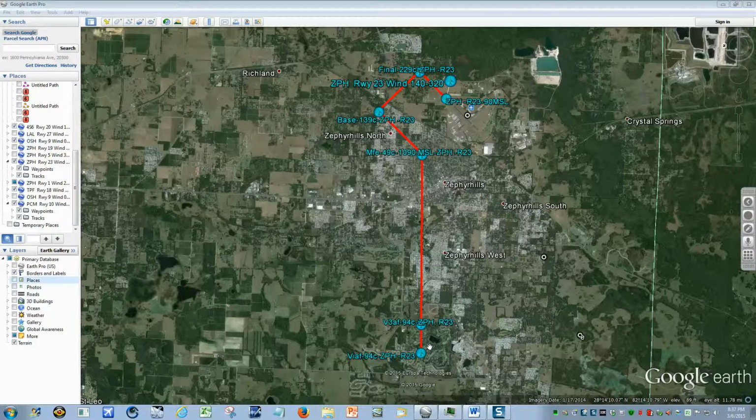Using our conservative 8:1 glide ratio, we multiply our anticipated altitude times 8 and extend the circle from the flight path out to our calculated value. Now we can find the sites that are within gliding distance.